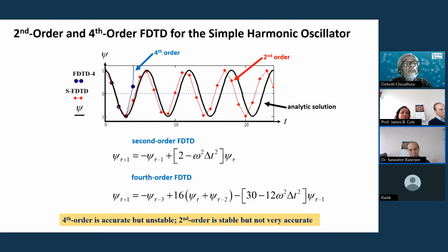So we must use more time steps. If we had our sampling so large that we only see 3 points of the sine wave, we wouldn't see anything. We would just see 0.